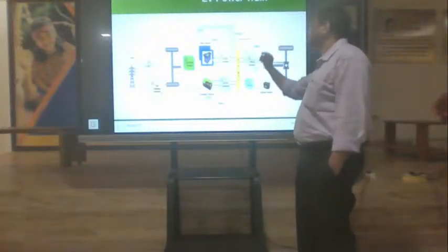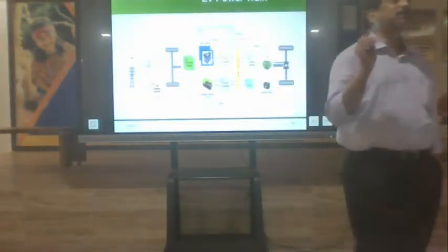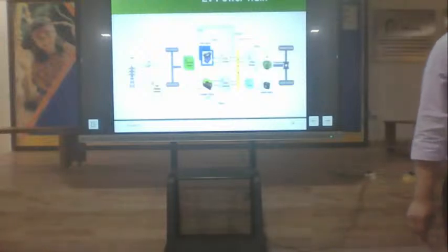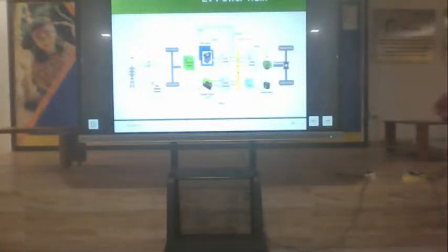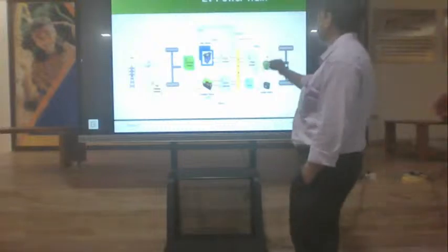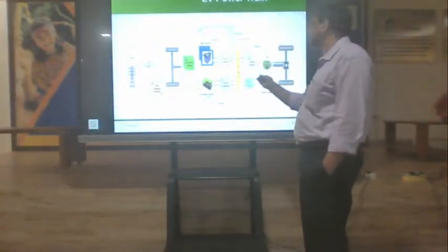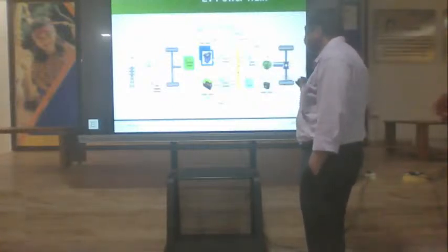Say this HVDC bus which is there, it is a 750 volts DC bus. Okay, from 200 volts, it is getting converted to 750 volts by a boost converter. There is a boost DC-DC converter in the chain, and then there is a three-phase inverter which converts that boosted 750 volts DC to a three-phase supply that is driving your traction.